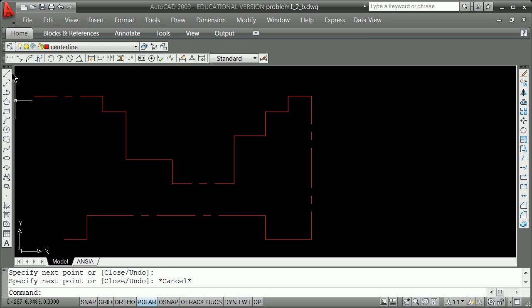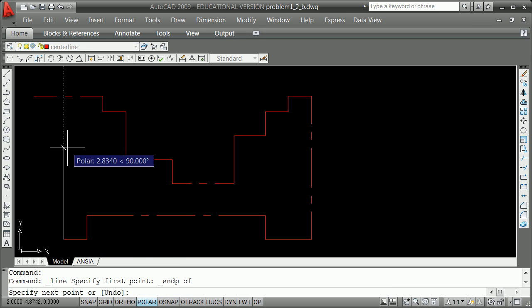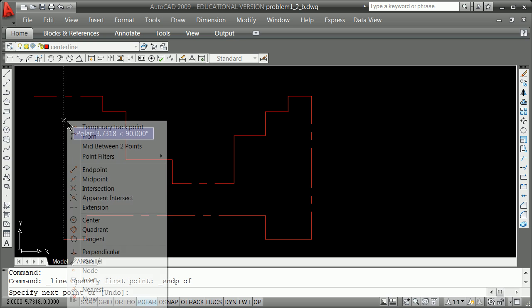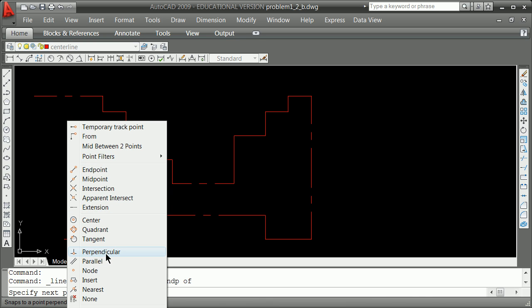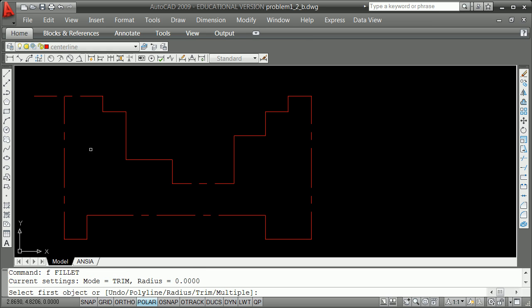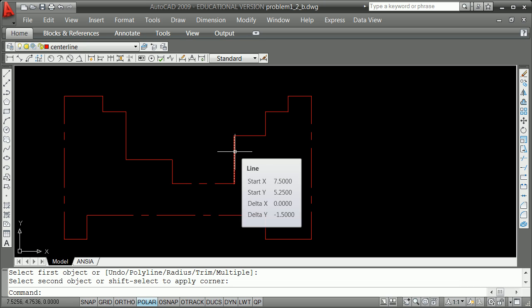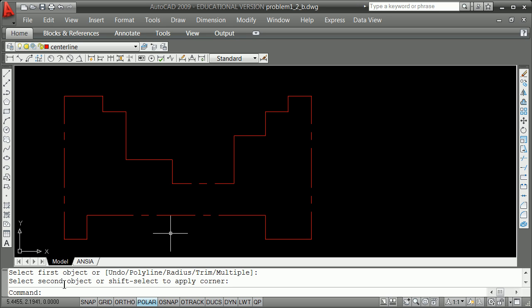And you might then go from a line from the endpoint here, either go shift right click perpendicular, which would be a good thing to do, and then still going back F for fillet, click, click, and having the shape. I will point out in doing that, I didn't necessarily keep all of these things going in the right direction because I skipped methods. So in fact, if what I had laid out here was a go-kart track where I wanted the things to go there and then take a left and then take a right and then right, left,